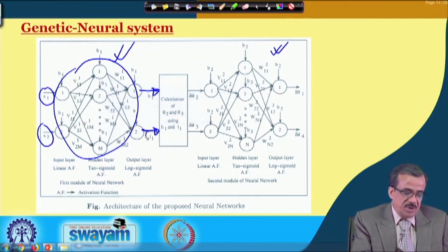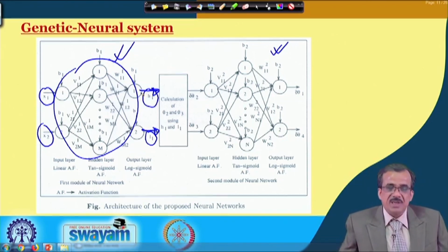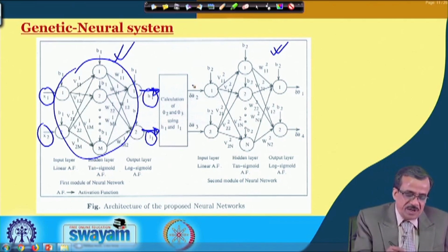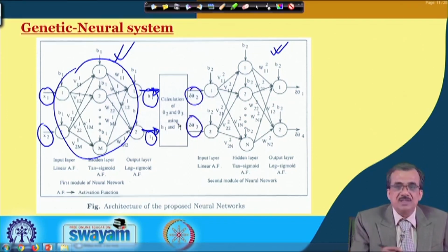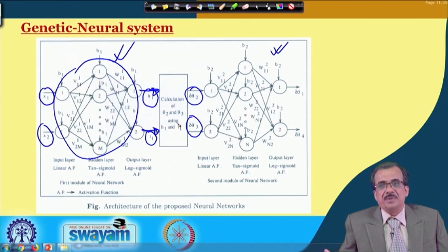That is nothing but your L 1, and once you have got this H 1 and L 1, mathematically, trigonometrically, we can find out what should be the joint angle. So, all the joint angles we can calculate except theta 4.